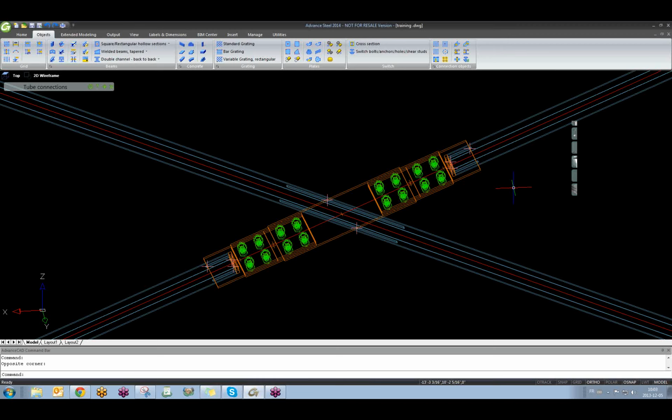This great shape in there, and I'm back over here. Okay, I've got this now. How do I get it? Well, what I've actually been doing instead of mirroring is just snapping it and then creating and copying the gusset plates. So just go to your objects, and then do an angle brace or whatever you're doing, and then just snap it from the same nodes again.